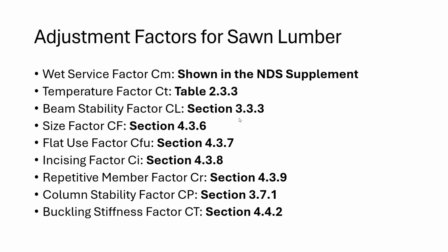So you'll see, especially in residential, that's why a lot of wood studs are spaced at 16 inches on center, because you're allowed to increase the strength of each beam or column by taking that layout. So again, for a one-off question, like, hey, analyze this glulam beam with X loading, you're not going to take the repetitive member factor into account. But if you have a question of, hey, this wall is supporting a load of 1 kip per linear foot, and studs are spaced 16 inches on center, you then will take that into account.